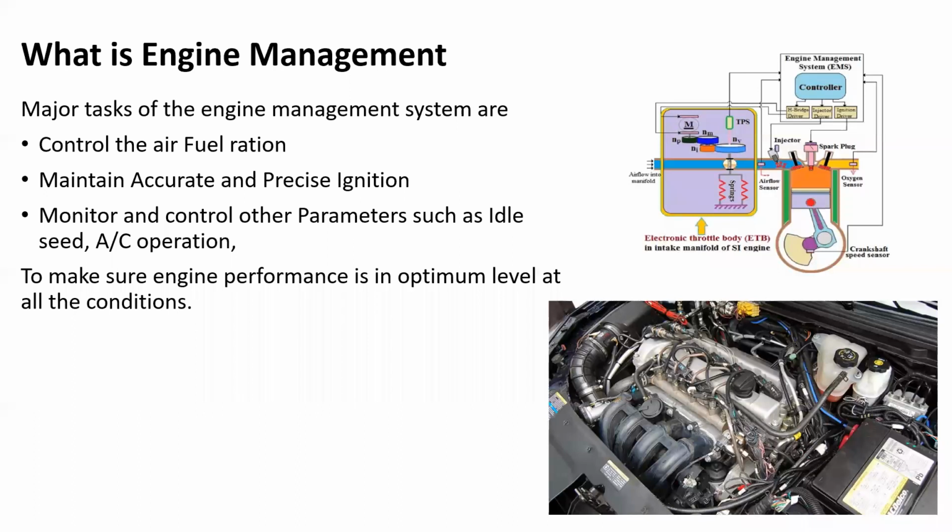That's not all, actually. For example, once you turn on the air conditioning, the engine gets additional load on itself, so it always has to overcome it, right? In addition, the engine has to develop a little more power to maintain all the electrical components that are operating, for example headlights. In such cases the engine has to change its normal idle control, idle RPMs and everything. All these things are managed, or looked after, by the engine management system.